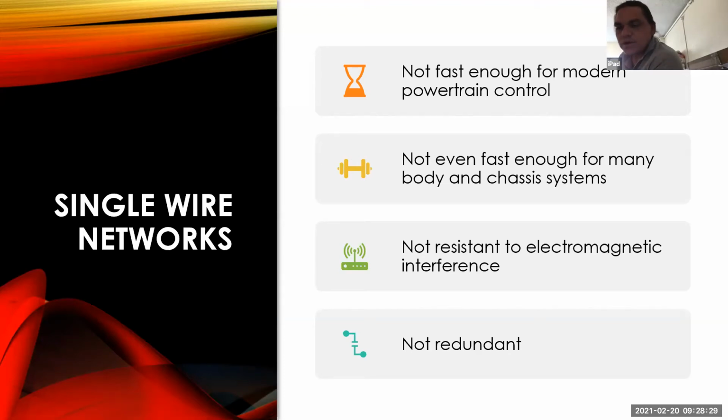RG56. Yeah, I mean, when I was in Ohio for some ADAS training a year and a half ago, one of the neat tricks they showed, we had a GM there. You want to diagnose the backup camera circuit. We unplugged the backup camera and hooked up Pac-Man. And when Pac-Man showed up on the dash, guess what? That means that the radio assembly and the coaxial and everything's good. The camera's bad. No, I mean on the core, like self-driving, they need it fast.